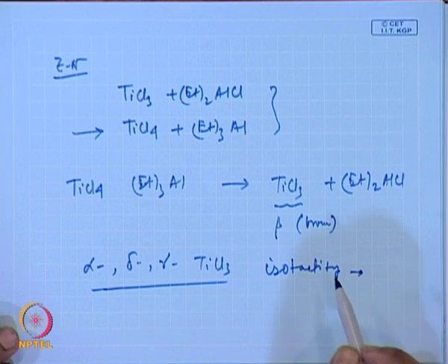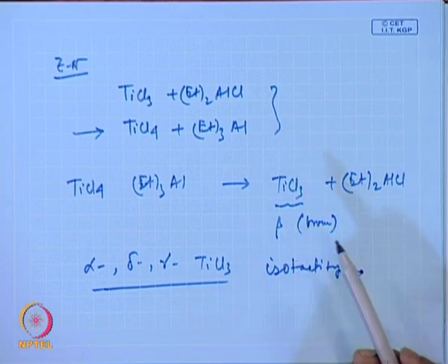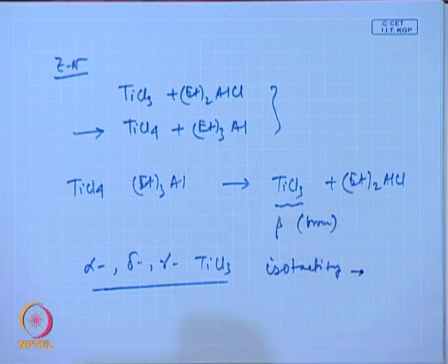Generally, when the polymerization is made, these two components are mixed and ball milled, that is, mechanically ground. That also increases the surface area of this catalyst. We will see in a minute how the surface area is important for this catalyst, and it also helps increase the activity of the polymerization.